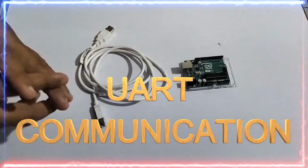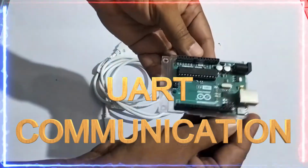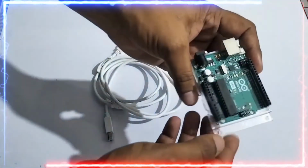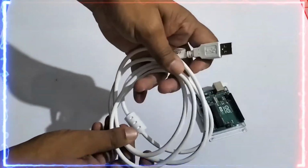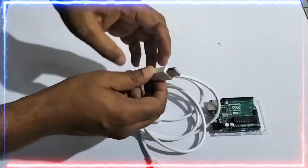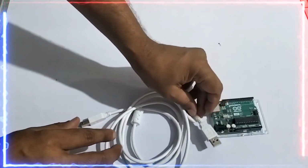So today we try to see the UART communication from the Arduino board, friends. This is the Arduino Uno and it has the ATmega328 microcontroller. In order to communicate with the PC, we have a USB A to USB B cable, friends. This we need to connect to the board and to the PC. We are using the Windows operating system in this experiment.